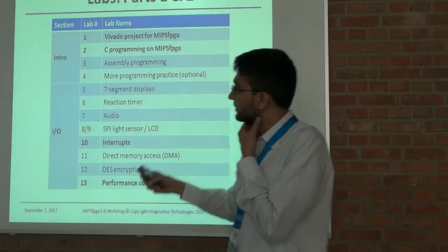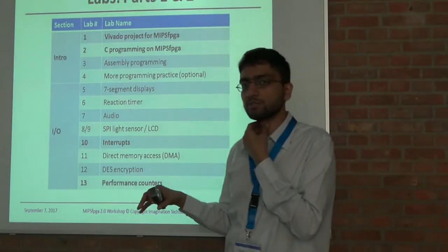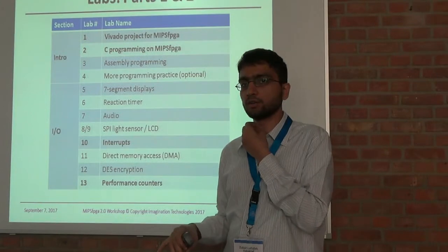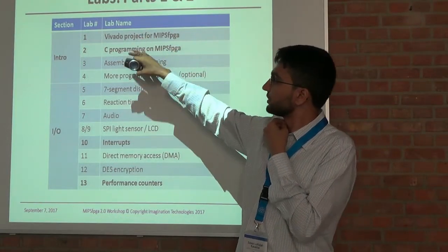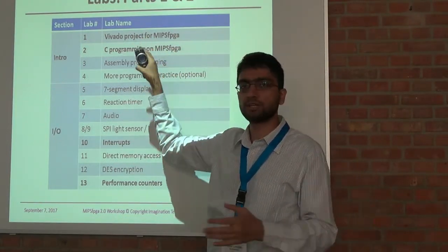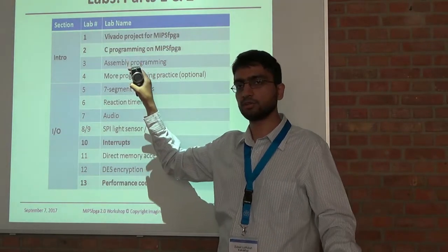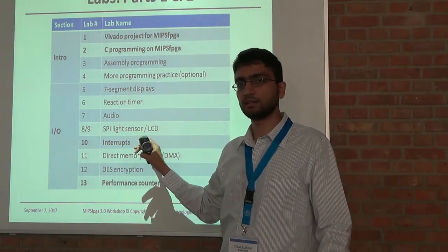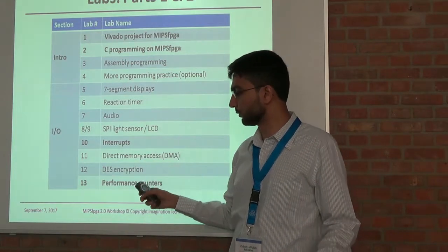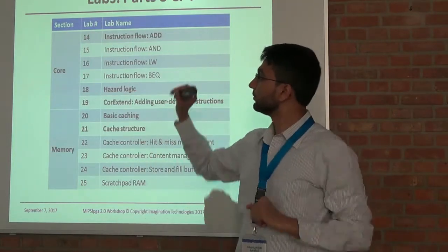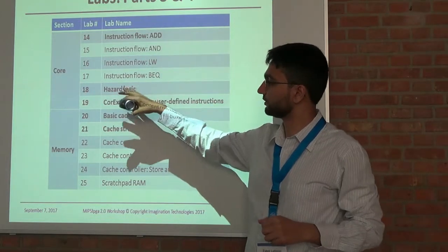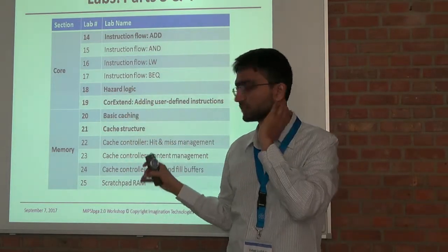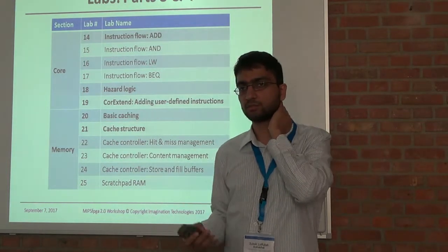Okay, so here's a breakdown of all the labs in it. The bold ones are the ones that we will be covering today. Okay, Vivado project, just loading the bitstream, C programming, how to load the code onto the FPGA core. We'll cover interrupts and how interrupts are handled on MIPS. We'll cover performance counters, and then we'll cover instruction flow. We'll cover some hazard logic, basic caching and cache structure over the course as we go forward.